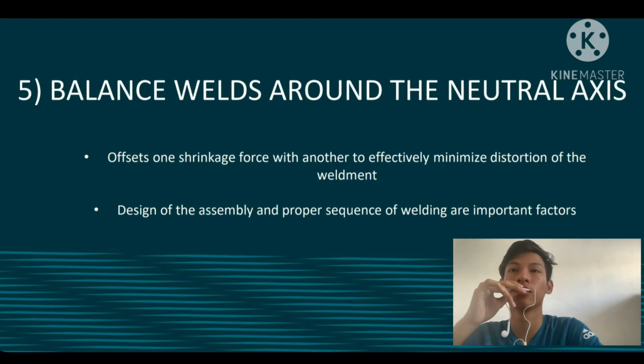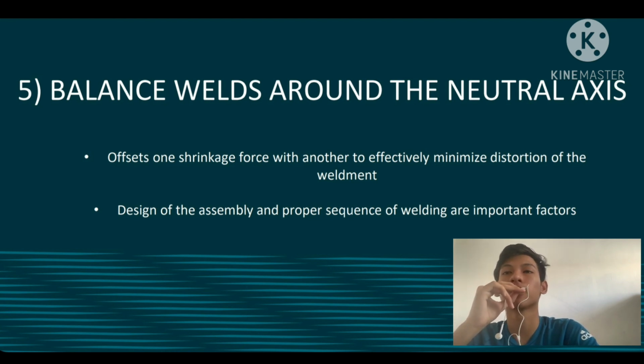Balance welds around the neutral axis. Offset one shrinkage force with another to effectively minimize distortion of the weldment. Design of the assembly and proper sequence of welding are important factors.